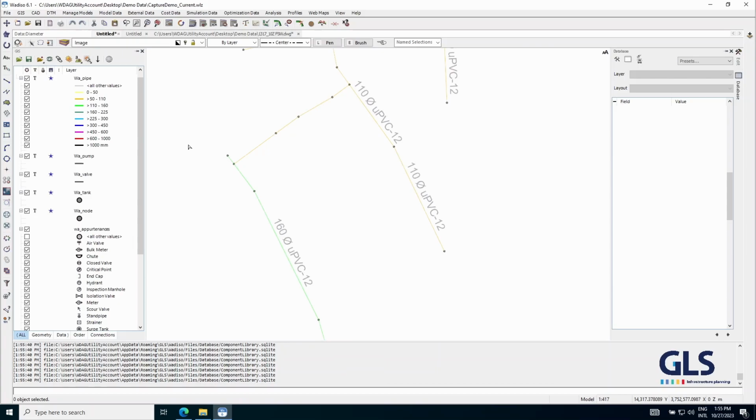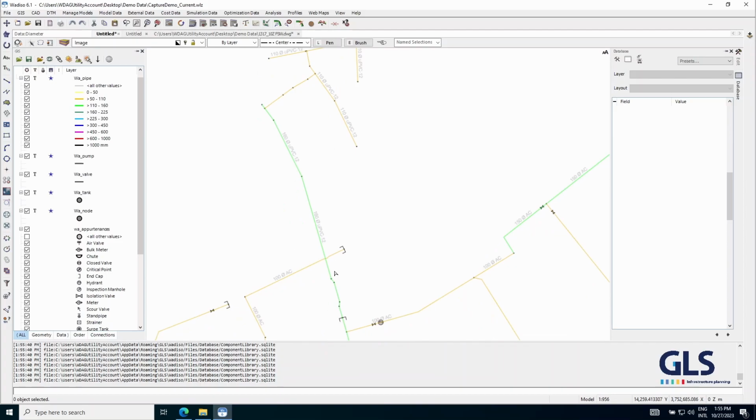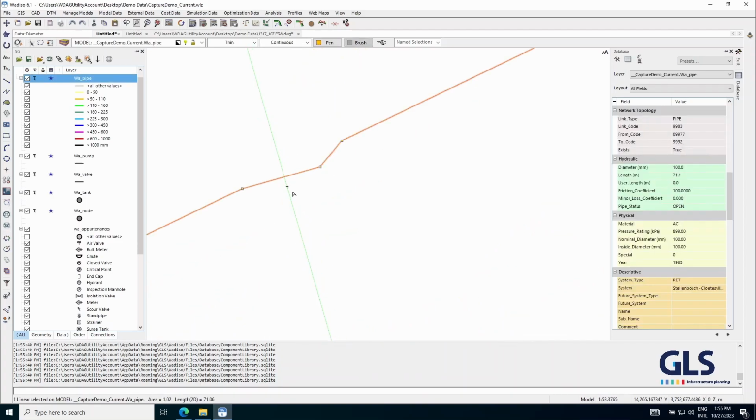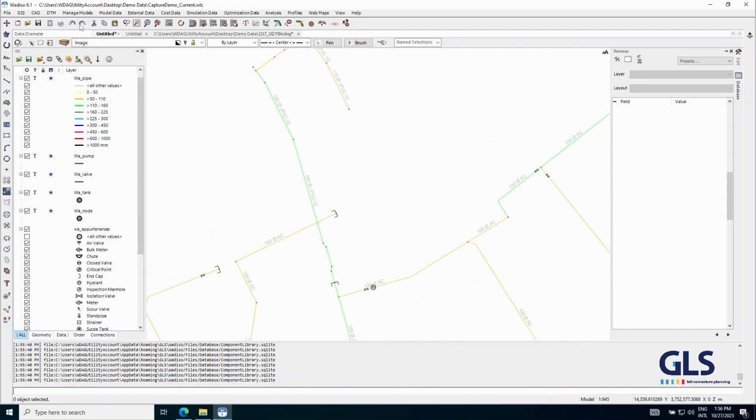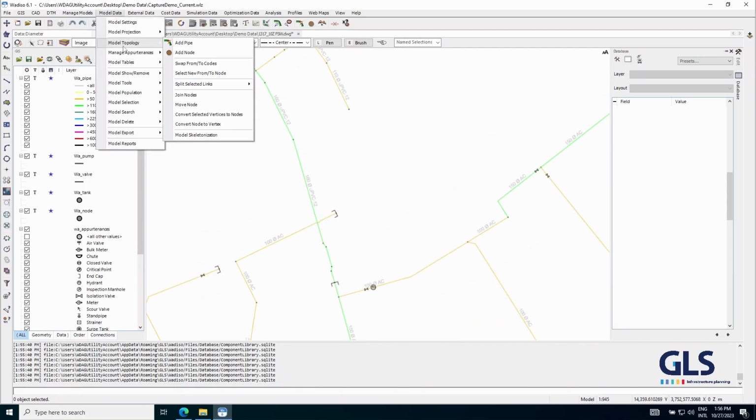Again, with the CAD and GIS, you have all your valves, you can do that manually. However, the next step we can see here is that with the CAD or GIS import, there is no automatic cross point or crossing pipes that are inserted. But what you can do after the creation or importing from GIS is run certain topology functions. So we have a show remove of intersecting links so that you can go and inspect on those locations if in fact it should be matched or not.